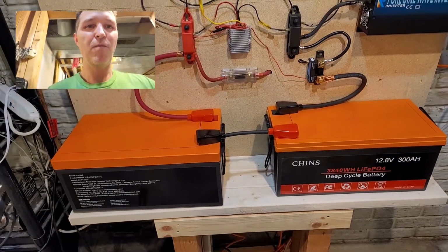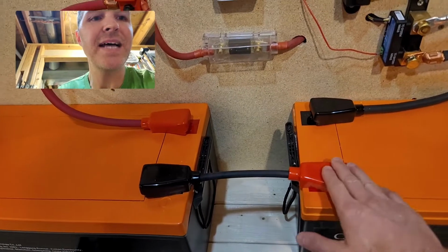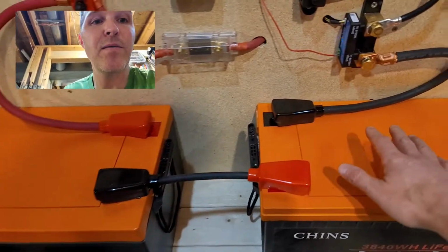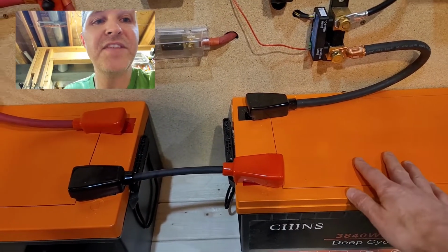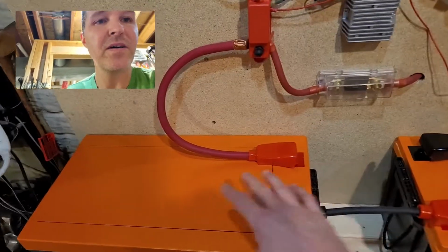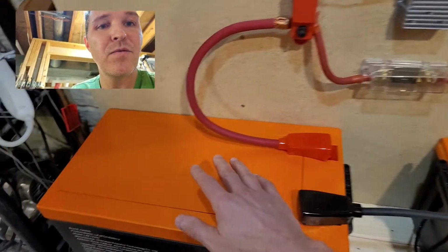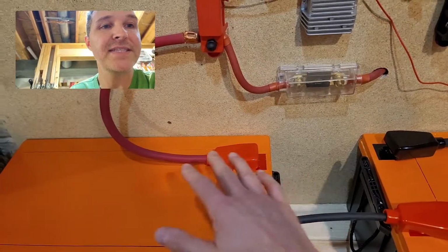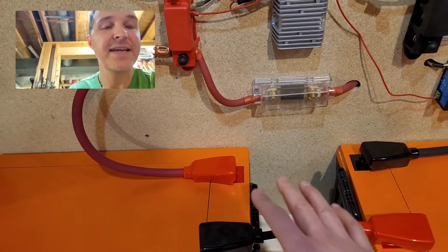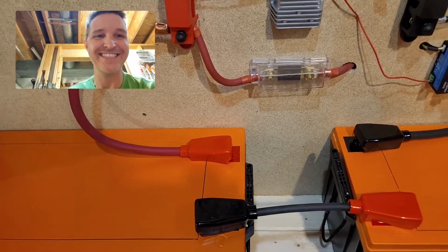And we're going to have it connected to the positive of the battery closest to the shunt. That way it's going to read the voltage of this battery and compare it to the voltage of the whole system. So it will know the whole system minus this battery equals this battery, and then it will be able to tell the difference between the two batteries, and it will tell me in percentage what the midpoint voltage deviation is.